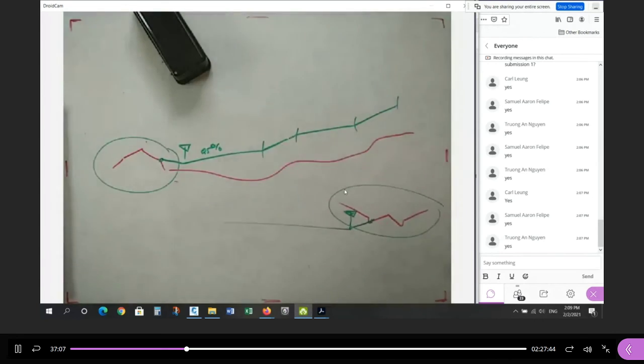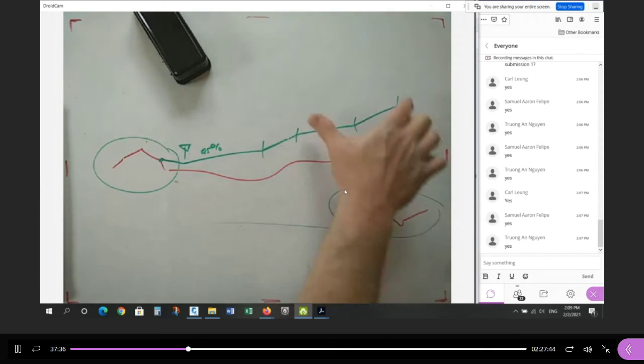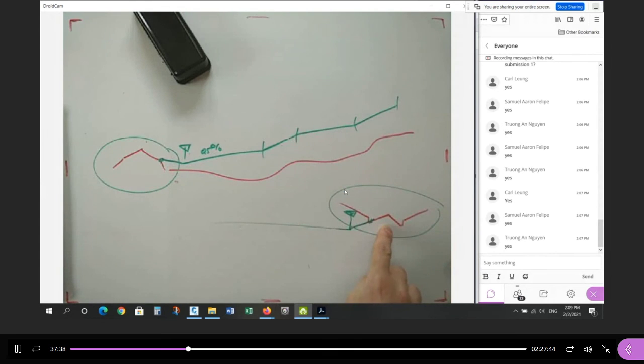So the original ground topo is from before the existing road was constructed. So I don't have this on my surface, and I don't have this in my profile. Okay? So what I'd like to do is create the surface of the corridor for Ledger Way, by creating the plan, the profile, the cross-section, a corridor, and then a corridor surface, so that I can model the proposed road and just treat it as if it's existing.